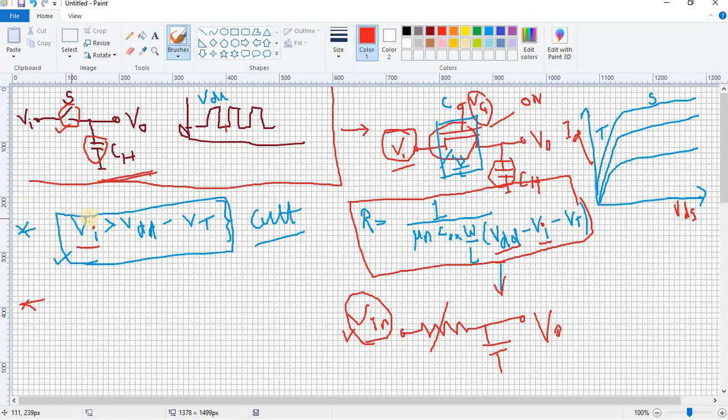If Vi is small, it holds good and it can transmit easily, so NMOS is effectively transmitting 0 better. And if we consider the case of PMOS transistor, there should be a lower limit for the MOSFET to work, right? We will discuss this later.